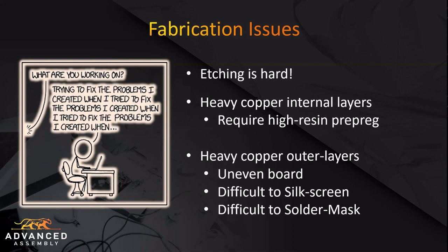Plating is also very difficult, but for different reasons. An electroplated board doesn't always plate at right angles to the board surface. Especially with today's technology, you need more of a pulse plating approach, which uses rectifiers and actual programs to throw copper from the anodes onto the panel itself, rather than the old school way of using DC plating.